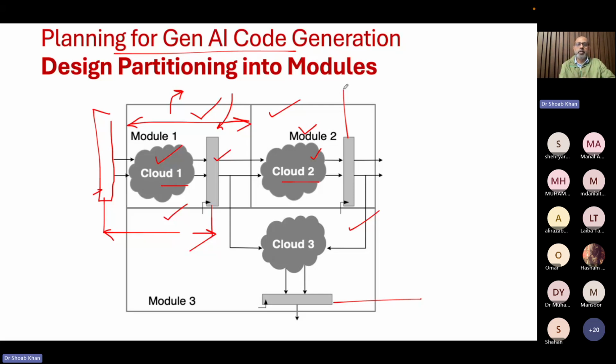So please remember that the output of your partitioning should be such that output values are always stored in a register. Another important thing, don't force yourself to intentionally put registers in your module so that your outputs are stored. They should be part of the architecture. So you are never ever going to insert registers in your code so that you meet the timing, because you cannot just go and insert registers. It's because they have implications.